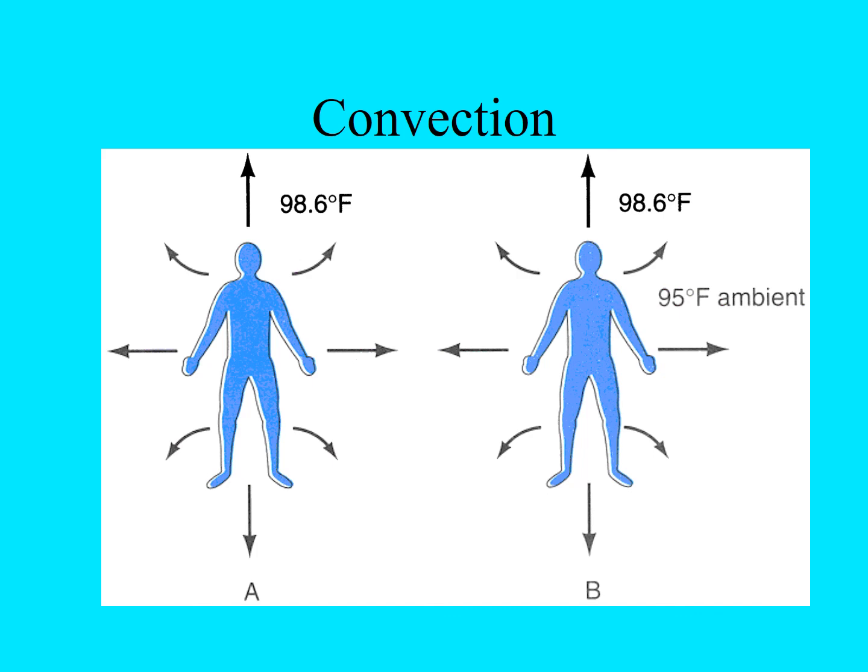Drier than that, we might be a little uncomfortable, but higher than that, we definitely start getting very uncomfortable. We've all experienced a very high humid day in the summertime, and just because of that, we're very uncomfortable. So one thing the air conditioning system does is dry the air out, or dehumidify it, make it drier, so we're more comfortable, as well as cooling the air.